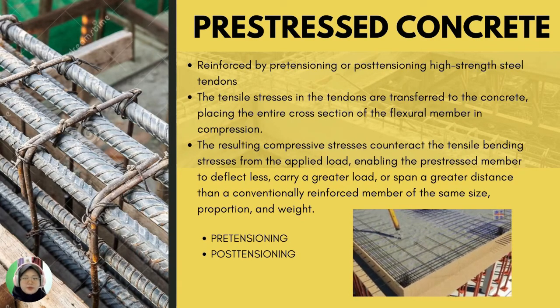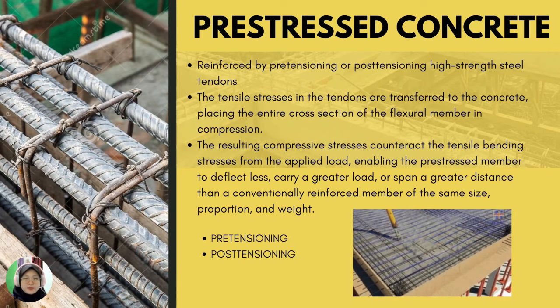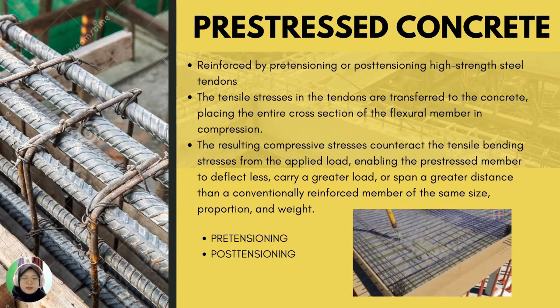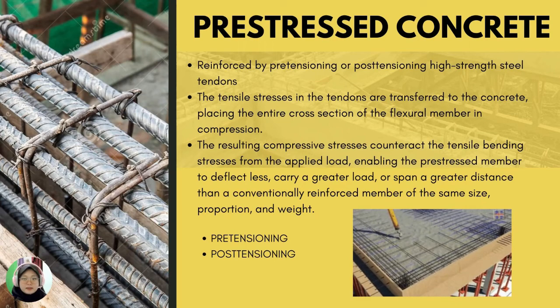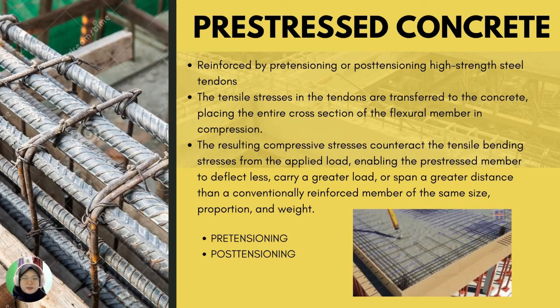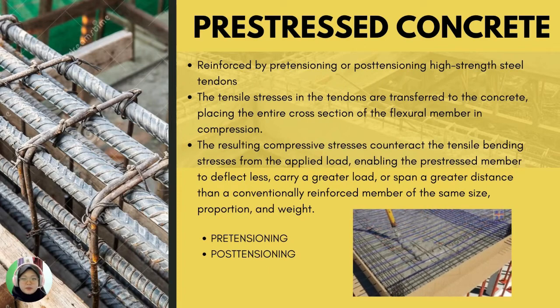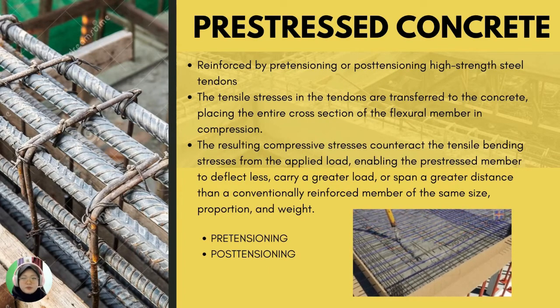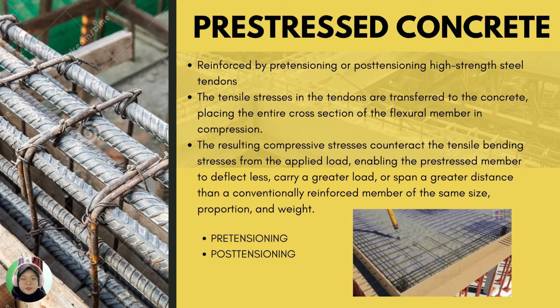Pre-stressed concrete is reinforced by pre-tensioning or post-tensioning high-strength steel tendons within their elastic limit to actively resist a service load. The tensile stresses in the tendons are transferred to the concrete, placing the entire cross-section of the flexural member in compression.